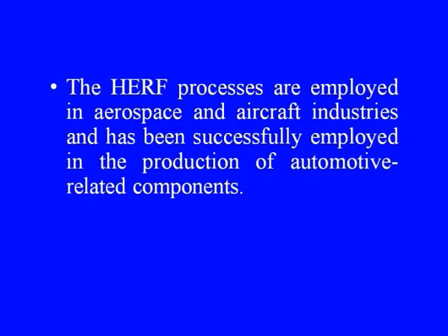This helps in reducing spring back as well. Then high energy rate forming can produce components large in size with a great deal of detail and superior tolerances. It is particularly useful for very large parts like domes, etc.